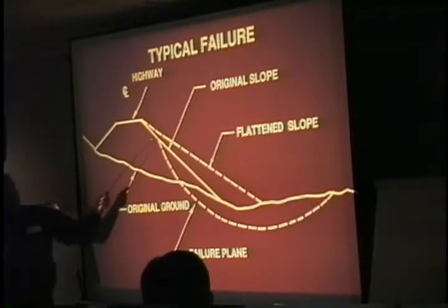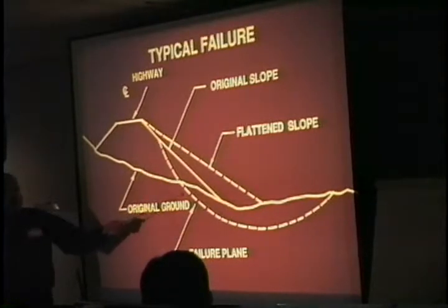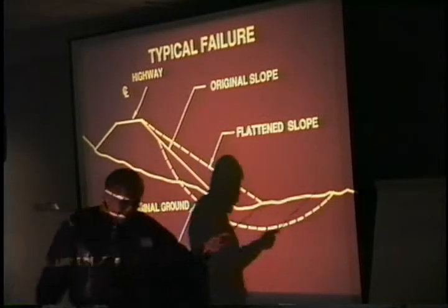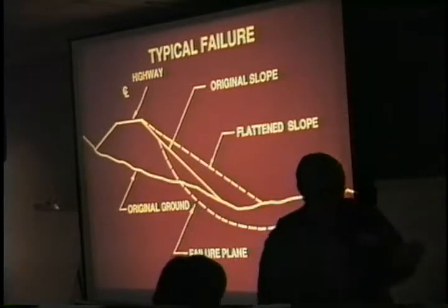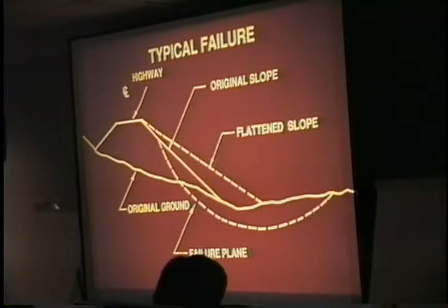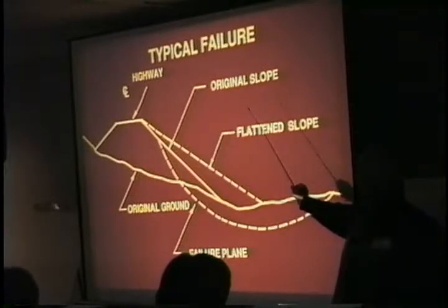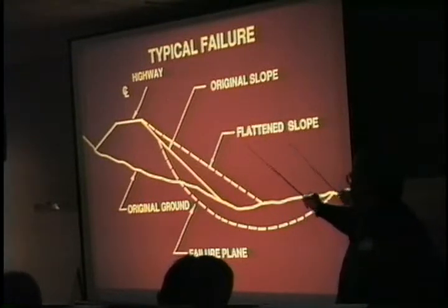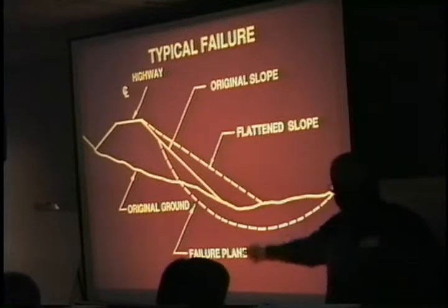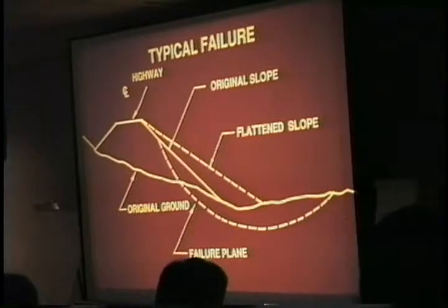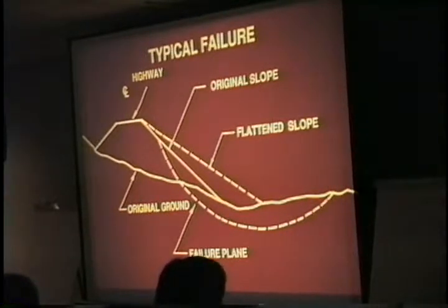We've already shown where the failure surface is here. We've done some analysis and subsurface investigation, and we know what's happening. Maybe we have some instrumentation that showed us where that failure surface was. So the answer here was, this correction method is not going to work at all. In fact, what we may be doing is actually adding more weight to this slope.